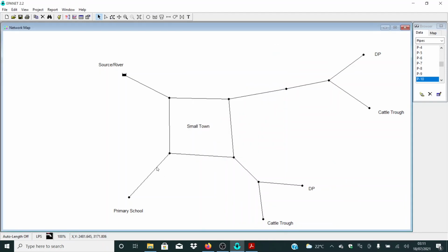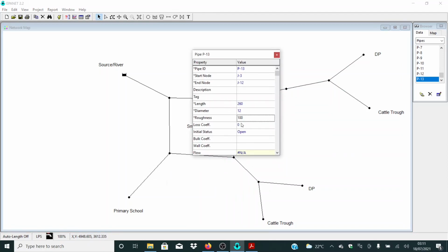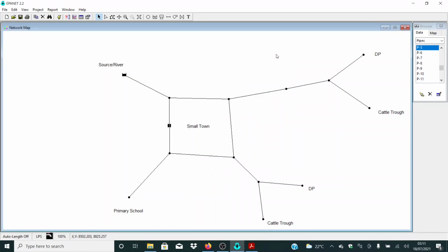And again, for this area, let's assume we are using a plastic pipe, so let me select 0.035. For now, our roughness coefficients are well set. What we need to do from here is to run our model, at least to see what we are getting.